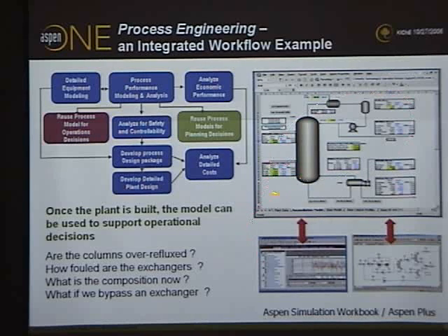An operator may look at a model like this to run cases to decide how to get around the current operating problem. How much should I increase the reflux ratio to get the temperature back into spec? So these types of simple interfaces allow you to continue getting value from your models after the plant is built.